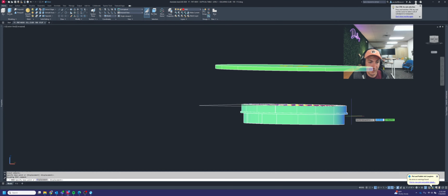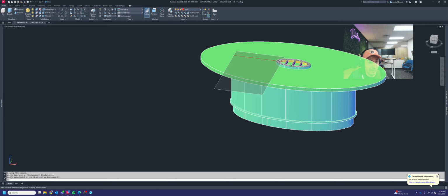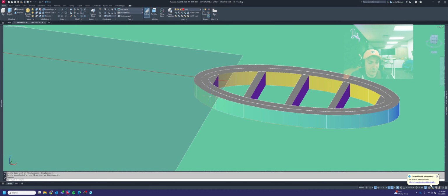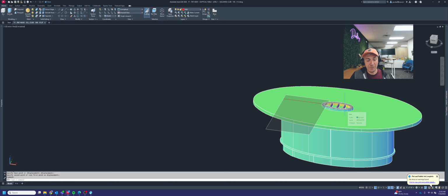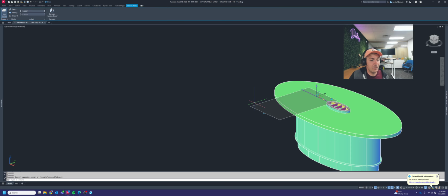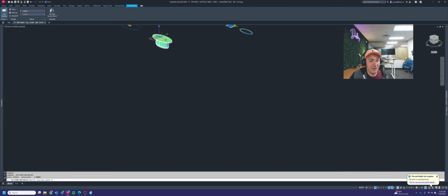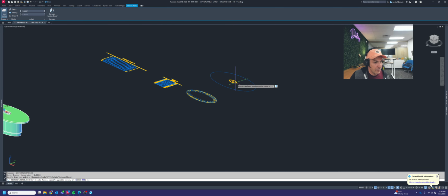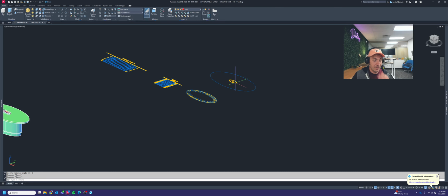All right, and then we need one more horizontal cut through of our little table / island here. And that's going to go through this. I want to show how these ribs look in here. And the only way to possibly do that is to make a horizontal section through that. So we're going to do that here. We're going to generate section block. And then we're going to hit create right here. All right, so 1, 1, 0.